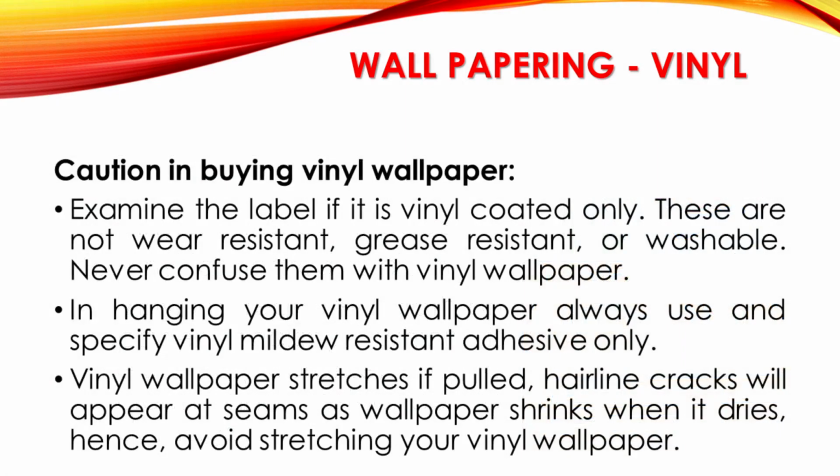There are three cautions in buying vinyl wallpaper. First is to examine the label if it is vinyl coated only. These are not wear-resistant, grease-resistant, or washable. Never confuse them with vinyl wallpaper. Second is, in hanging your vinyl wallpaper, always use and specify vinyl mildew-resistant adhesive only. And third is, vinyl wallpaper stretches if pulled. Hairline cracks will appear at seams as wallpaper shrinks when it dries. Hence, avoid stretching your vinyl wallpaper.